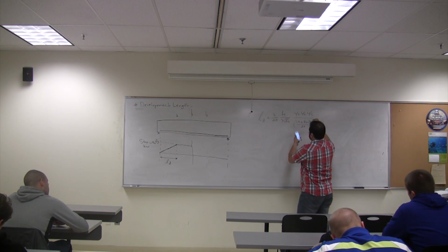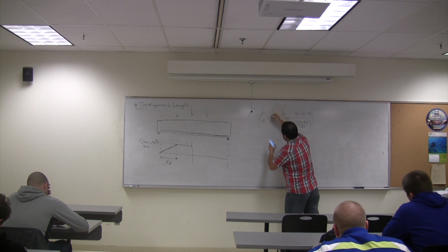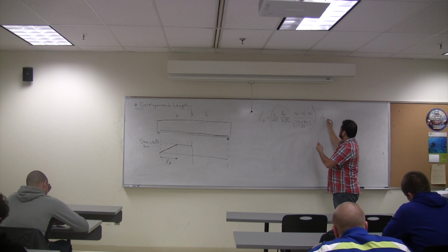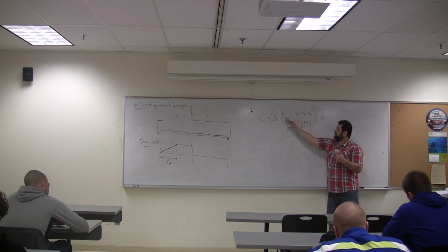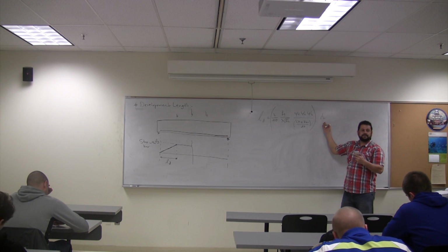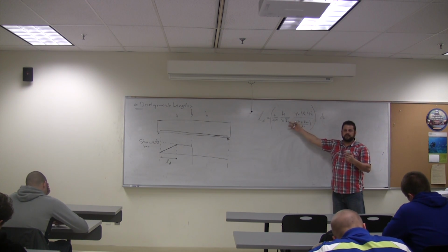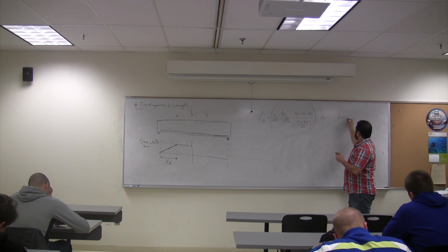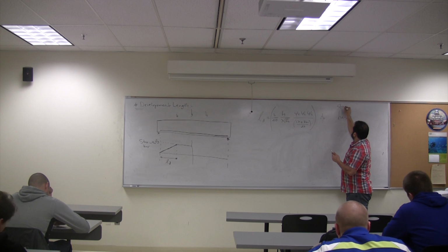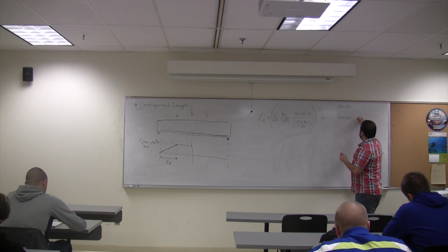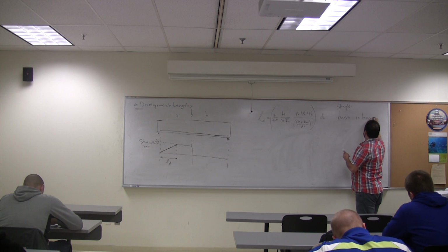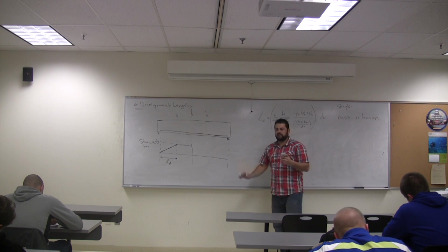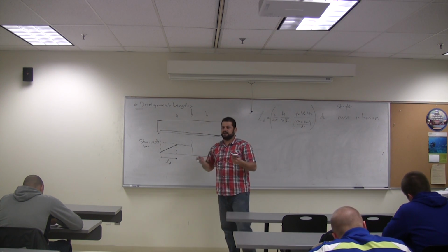See, all of this here is a factor multiplied by the diameter of the bar. Everything in here is multiplied by db. What's this required development length? That's the ACI requirement for development length for straight bars in tension. That's the maximum development length you may calculate when the bars are straight and in tension.